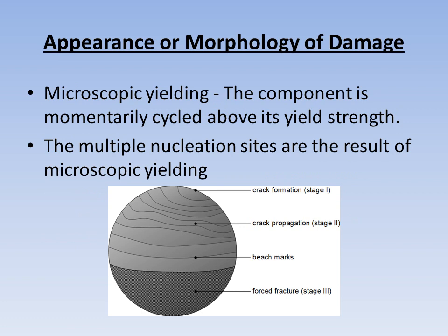For materials with endurance limit, there is a relation between the endurance limit and ultimate tensile strength, that is UTS. Endurance limit divided by UTS is equal to 0.4 to 0.5, or otherwise we can say that endurance limit is 40 to 50%.